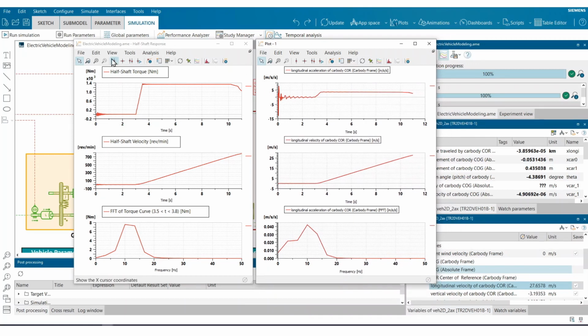As observed from the FFT plots, the frequency of oscillation of the drive shaft is at 10 Hz. The same response is also observed on the target location C-track. If, during a certain scenario in the design phase of vehicle systems, this is not a desired frequency at which the drive shafts rotate, it may cause unwanted vibrations in the vehicle. The drive shaft oscillations may also amplify other system resonances, causing higher target responses.